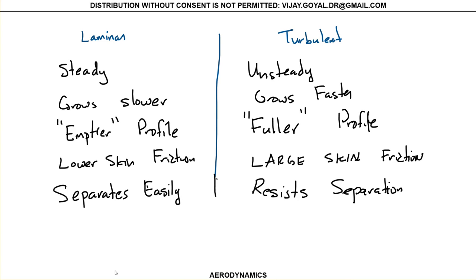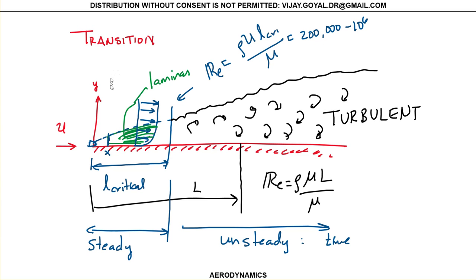And so, although we don't like the drag, here I can ensure that my fluid is actually sticking to the surface. Here I know that it will separate. And you can see from the picture I just drew, right? Somewhere in this region over here, you don't have any air actually sticking, because it's just starting as my velocity starts increasing.